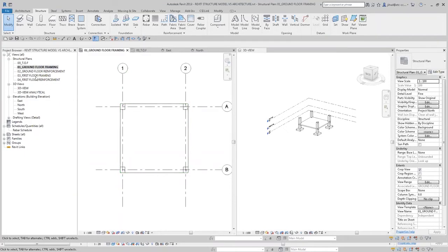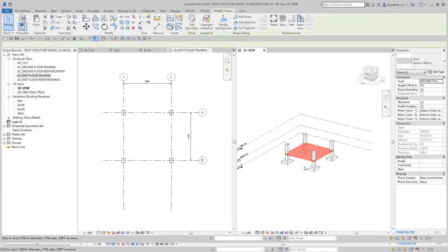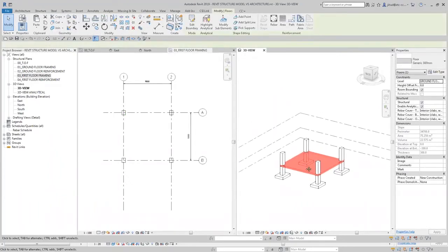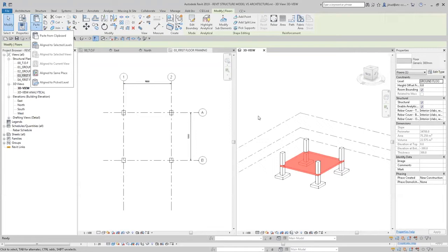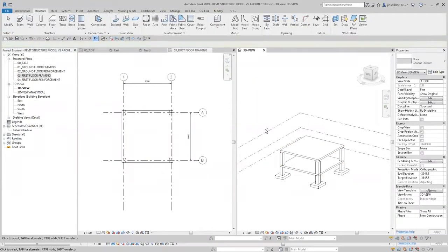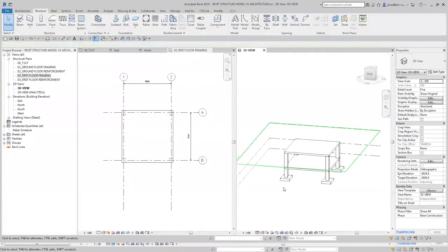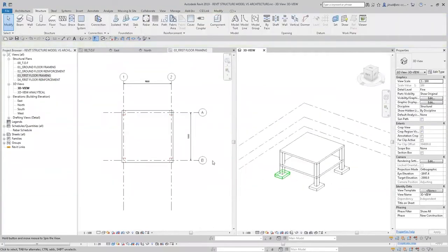We are, therefore, able to observe the design from whichever point we want. We will now move to the first floor framing, in order to design its slab. Revit resembles AutoCAD in this regard, so we can benefit from the various options that can help us, such as copy to clipboard, align to selected level, etc. This applies to floors, columns, beams, and almost everything else in Revit.